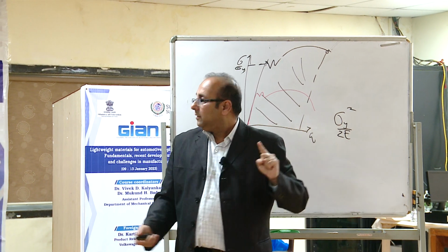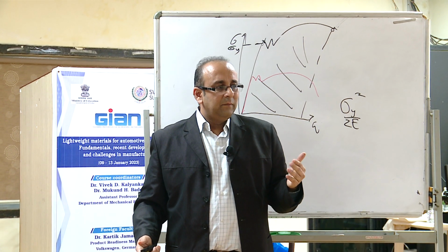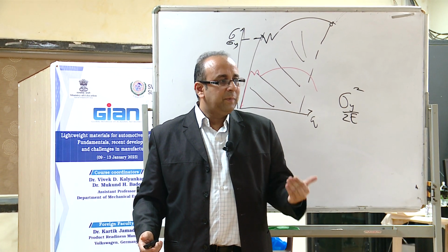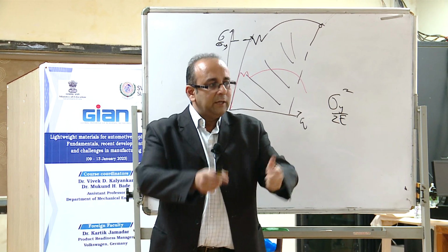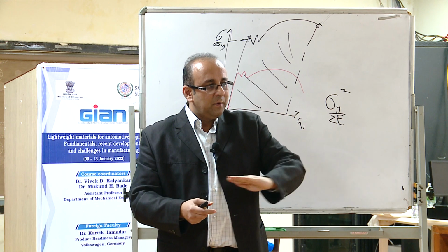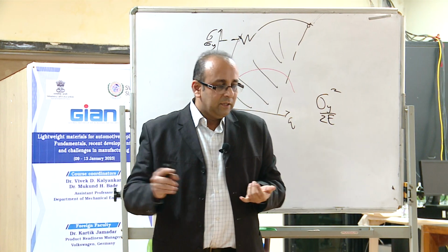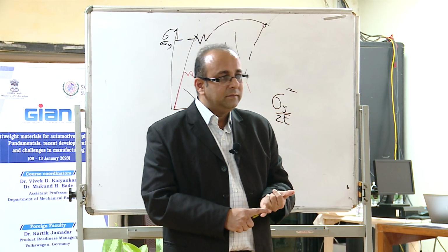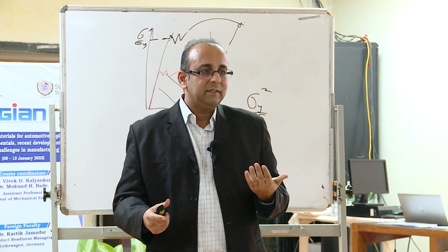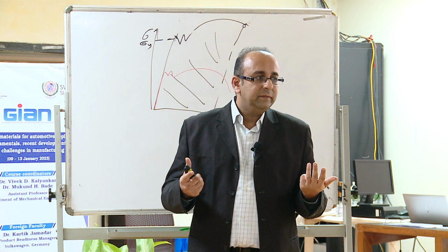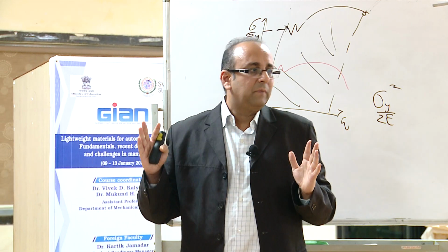Now here the part can be treated further with zinc, but that is also additional cost. So what people are using is aluminum silicon coating before that: put it into the oven, deform it, and the aluminum silicon coating will remain. There is no zinc coating necessary after that. So no zinc, no second forming, the part is feasible. And this part has extremely high strength, 1500 MPa, good deformation, a direct method used by most of the OEMs.